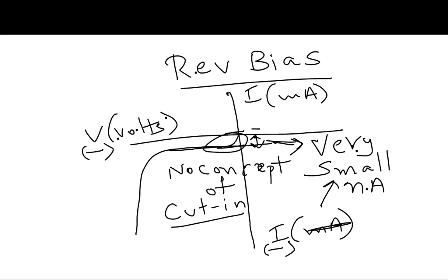Now, the minority carriers were formed, or they always exist, due to thermal conditions. It is the nature of physics. Thus, at a given temperature, they are constant, and thus, with increased voltage, these minority carriers do not provide an exponential growth of current like in forward bias. Hence, current in this stage is called the saturation current.